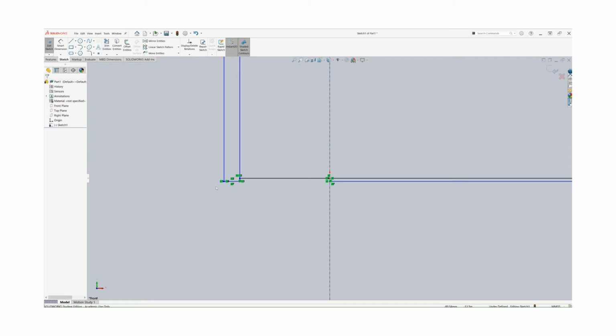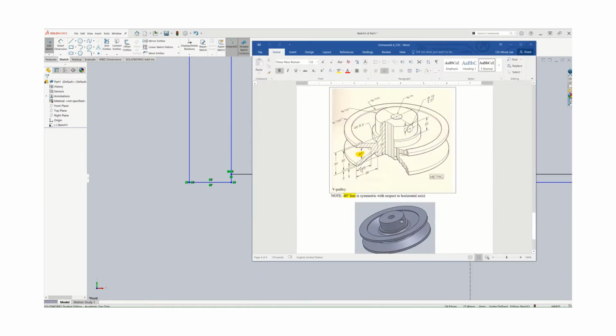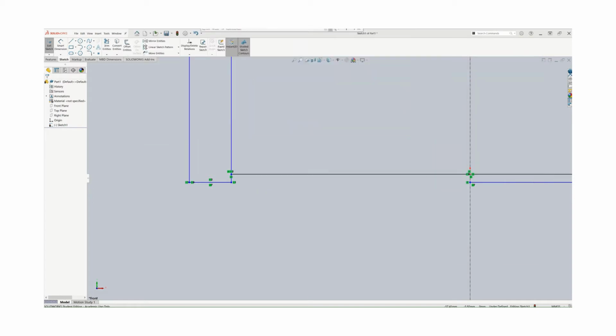Another thing is, if you look again at the bottom here, I will zoom in on that area. From the original drawing that we need, I need to have from the base. I just created the bottom one here, and from here, that tip of that edge right here, to have the angle line going 5 millimeters up, I could offset the horizontal element. So again, offset this element by 5, and in this case again going up.